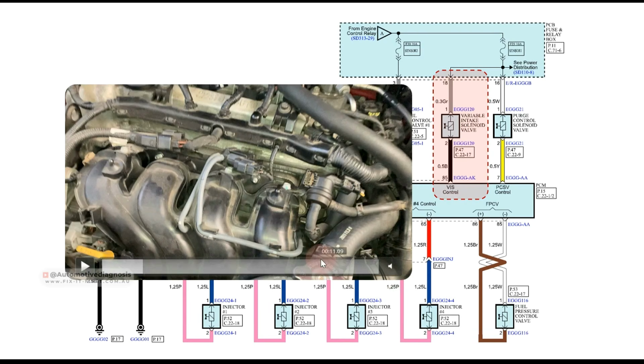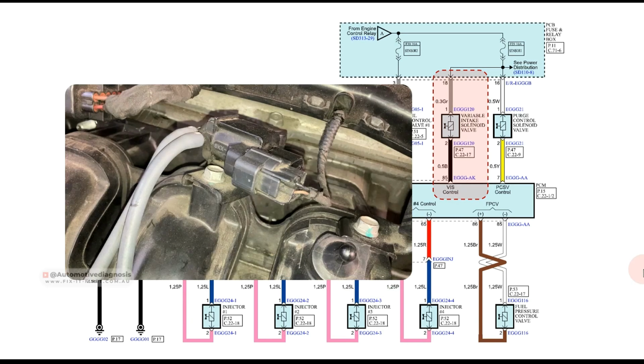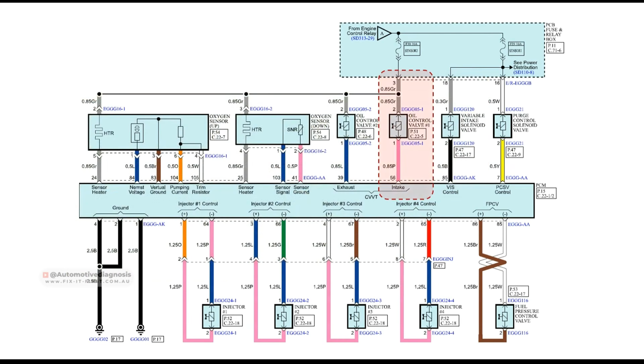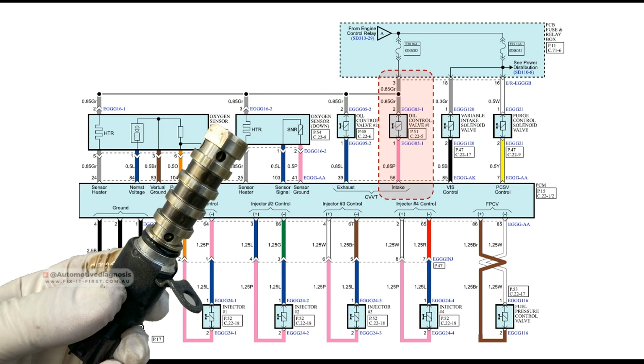And those valves are controlled by this diaphragm. On the valve, as you see, we have two wires. That gray wire is the power supply for this solenoid valve, that you should expect battery voltage when ignition switch is on. And this black wire is the control line.